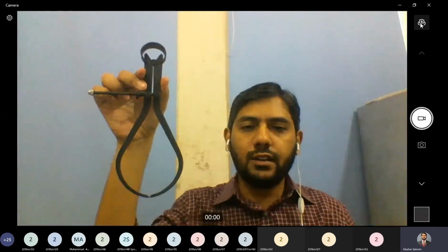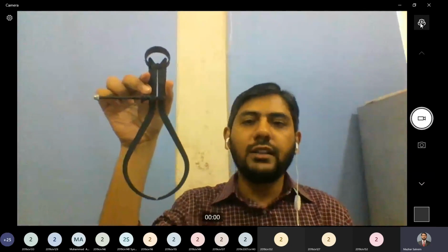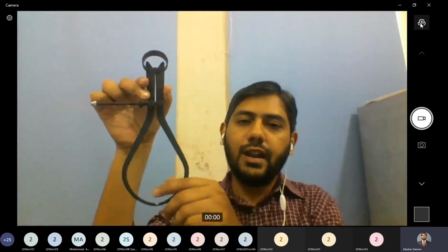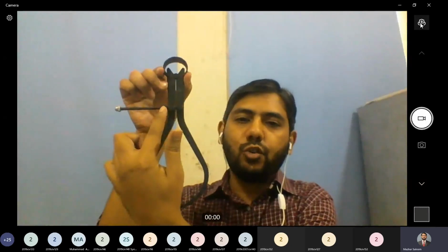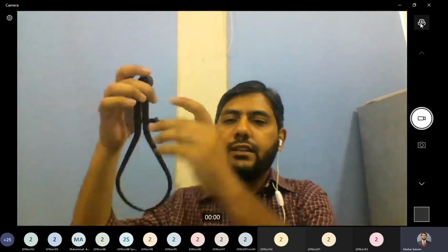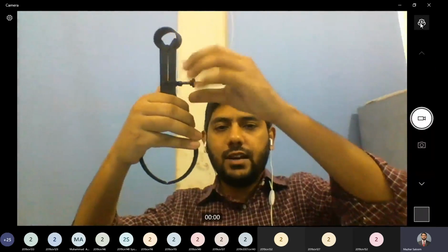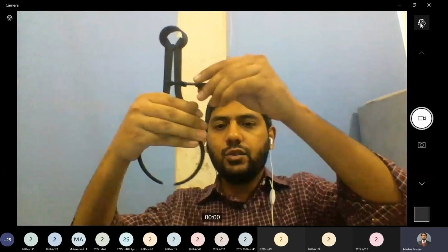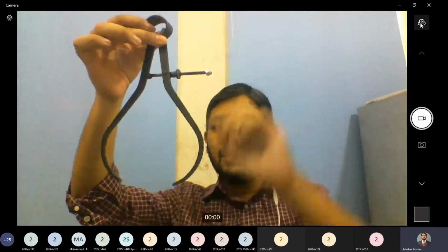It is used to measure the outside diameter and lengths of any object. Just like the inside caliper and spring divider, it has this lever and screw available. So with this, we can control the opening quite precisely. See, I unscrew this and then it opens up to this level and it remains fixed here.